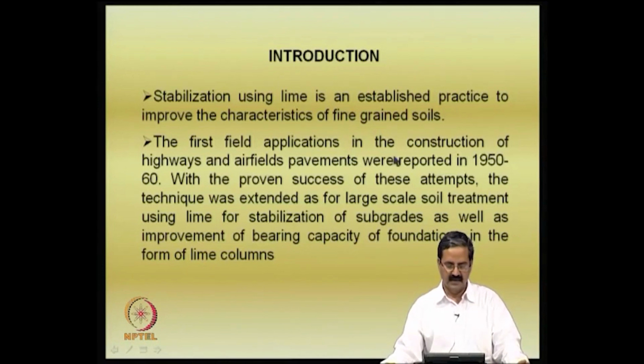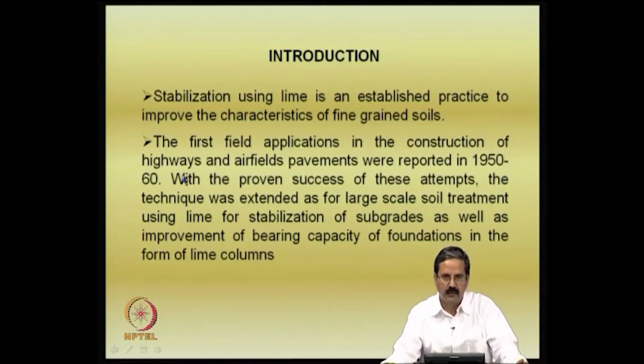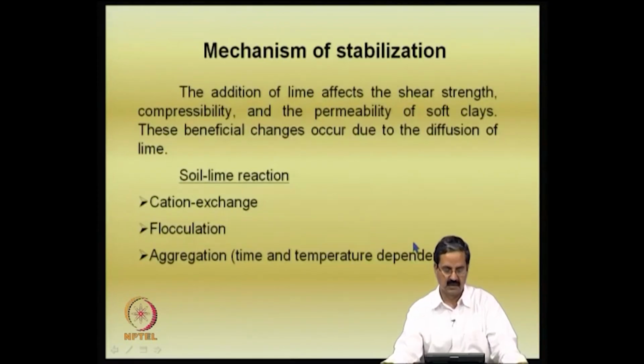The first applications in the construction of highways and airfield pavements were reported in the 1950s and 60s. With proven success of these attempts, the technique was extended for large scale treatment, using lime for stabilization of subgrades, as well as improvement of bearing capacity of foundations in the form of lime columns.